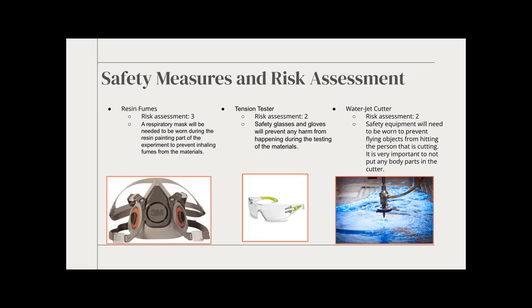And then the last thing was the water jet cutter, which we actually didn't have to do ourselves. We sent it to the lab, but the safety steps taken for that would be wearing safety glasses and gloves and all the proper safety equipment, and making sure that we wouldn't put any body part under it while it's running, because it would cause harm, and just staying away from it until it completed the job.